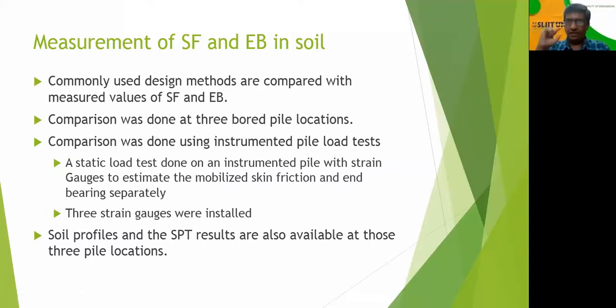If you look at the instrumented pile load testing, between strain gauges you can measure the skin friction. I am not going to go into the theory of doing that, but you can determine the skin friction. If you have another strain gauge at the end, you can determine the mobilized end bearing. Mobilized means what is there when we apply the loading. In each of these piles, 3 strain gauges were installed.